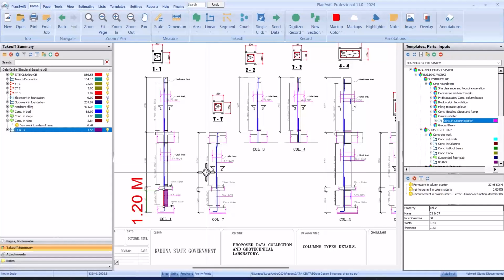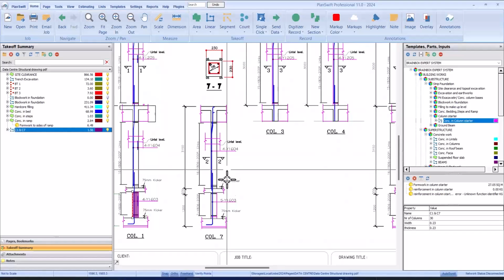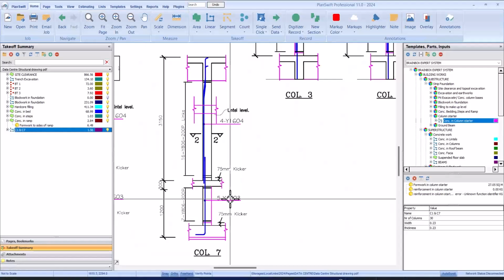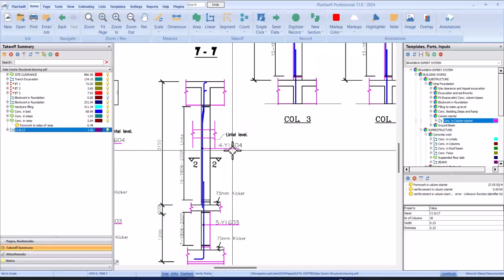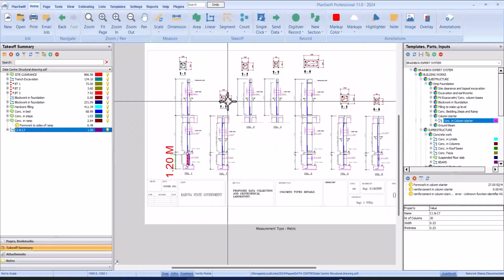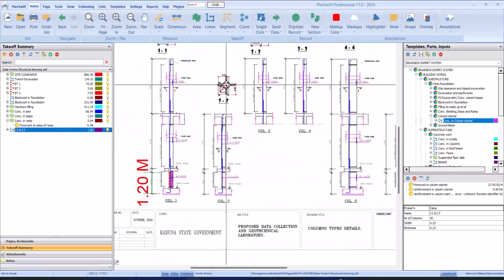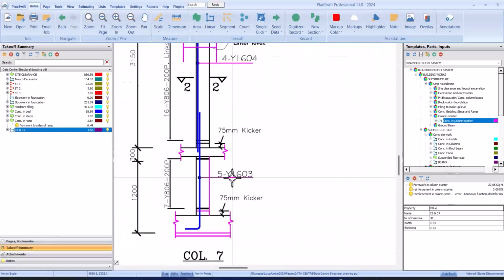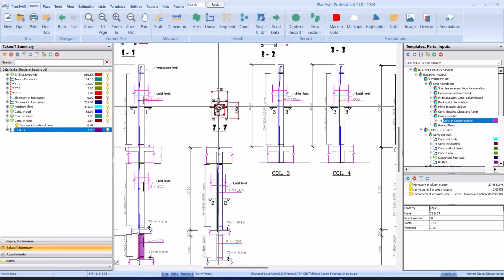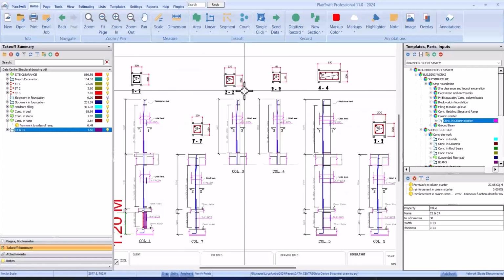So you can see, make it 30 numbers. And in here now, you can see we have some errors in the drawing. They're specifying 5 numbers here and then 4 numbers here, while in this section it is showing 4 numbers. So I think this is an error. Just go with 4 number. But you can decide to measure it and then make this one 5 number and this one 4 number. But me, I will assume it is an error and go with 4 number all through.